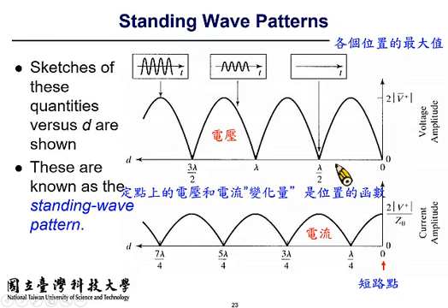If you do the test in the time domain with a voltage probe, you still observe a sinusoidal signal. However, the magnitude is smaller than the measurement at this position, and greater than the measurement at the voltage node. Similarly, if you use a current probe, you will get a similar result.